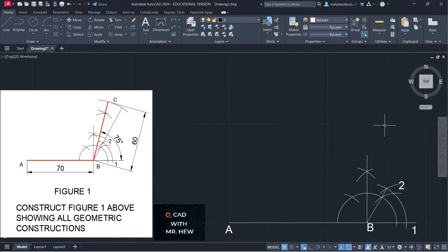What we're going to do is extend the line. So we're going to draw a construction line here, enter. Then we're going to type the word extend. Shortcut is EX. So we click this line, click that line. Okay, there it is, enter. What we're going to do is delete this line. We don't need it again. All right, good.